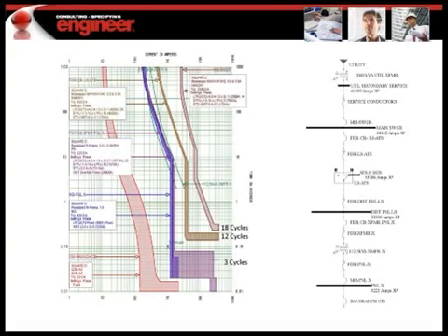Some manufacturers currently produce switches that are rated at 30 cycles. So in this particular case, we would likely have to specify that our transfer switch was able to tolerate 38,500 amps for at least 30 cycles. So this is an example of the impact that selective coordination has on the specification of automatic transfer switches.